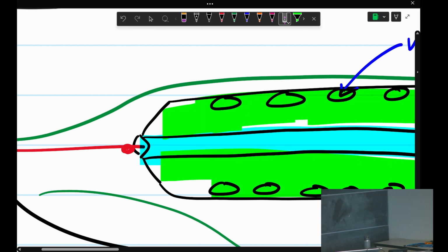So the velocity comes in there and you can see the little static ports as well as the stagnation port there. And these two ends are connected. There's a very small tube that runs inside this inner diameter all the way out, and that's our stagnation pressure. And then this other tube coming out is our static pressure. I showed you this before, it's like a differential pressure sensor. It's actually designed to be connected.